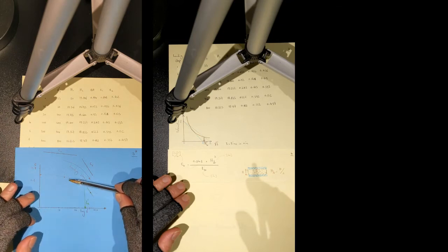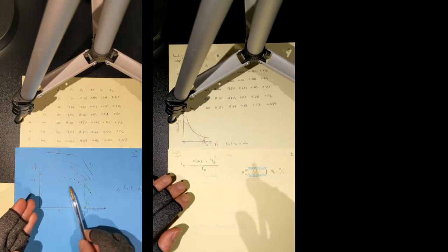Now, your diagram has two parts. It has a part which shows a very little change in void ratio with increasing effective stress. So it kind of tells you that the soil in this stage is pretty much strong. Over-consolidated line, if you remember.